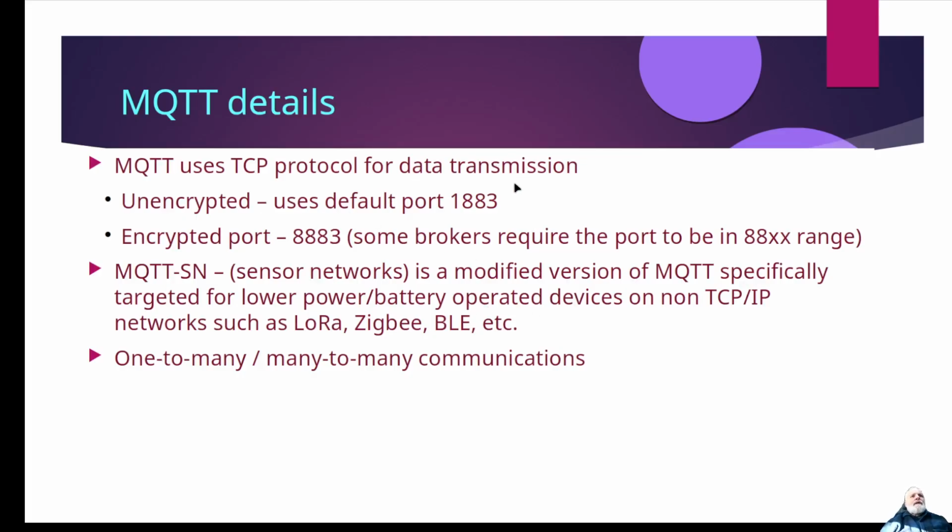So one of the things to keep in mind with MQTT is that, like any of these other communication protocols, they use ports. When we were using Node-RED, we had to go to the BeagleBone to the Node-RED service on port 1880. MQTT just happens to use port 1883, so I just keep that.